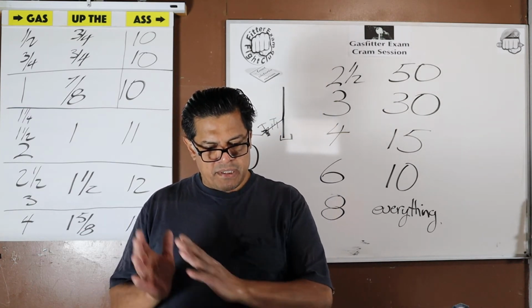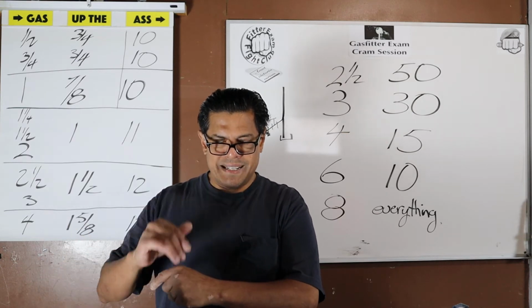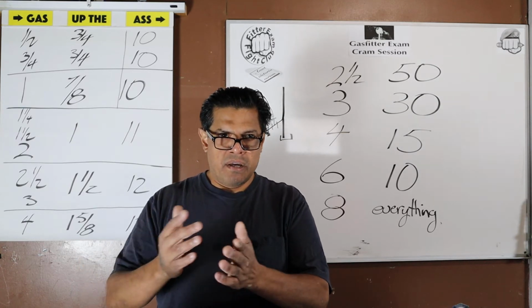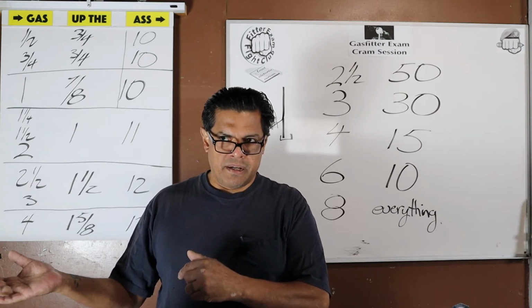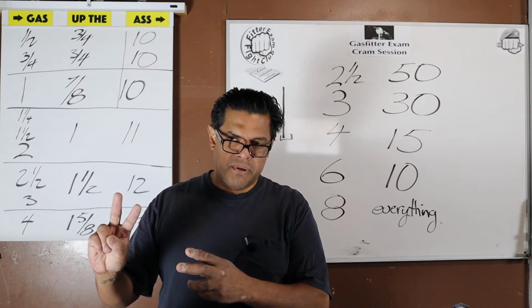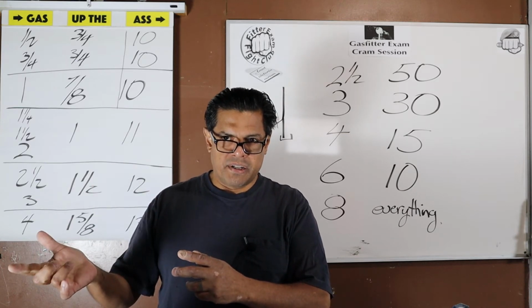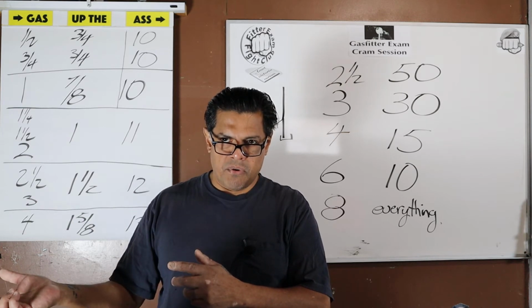When we were talking about the test T, that a test T or drip leg has to be downstream of a lockable supply valve, we mentioned that the test T, when we mentioned the drip leg, two reasons why we don't see it. The most important reason is to eliminate unwanted connections. Another reason is, we have dry gas, so we don't need it anymore.